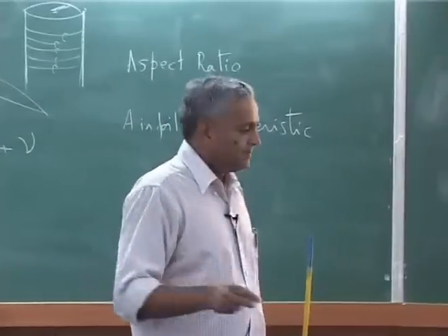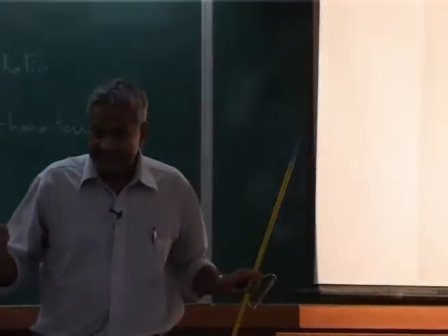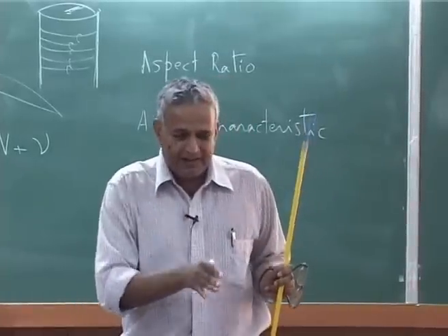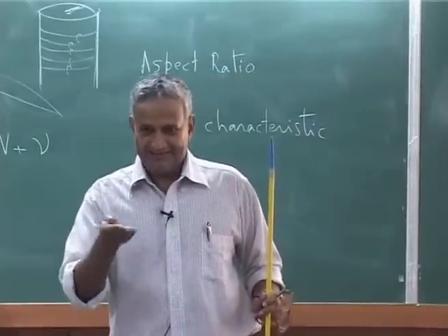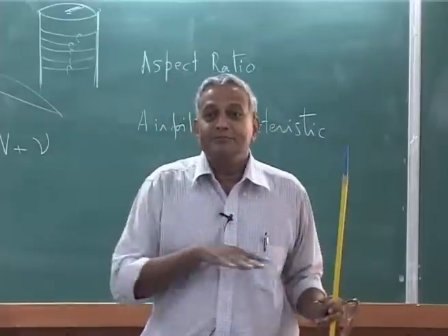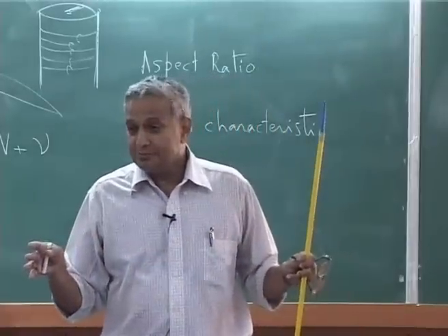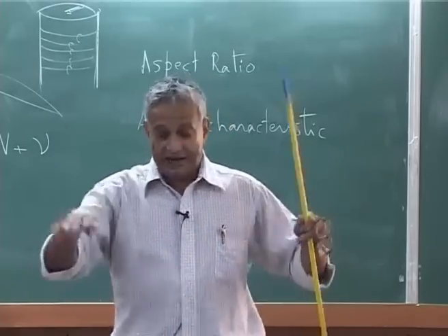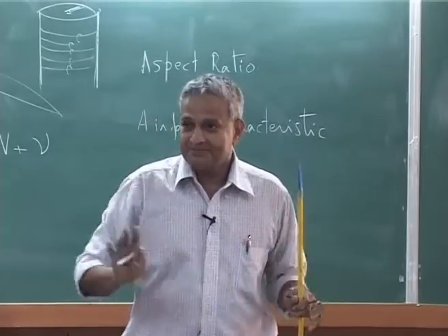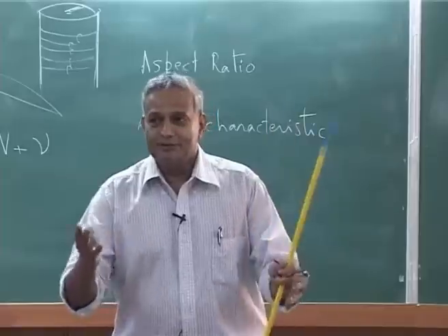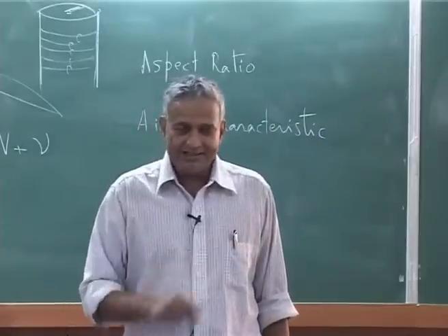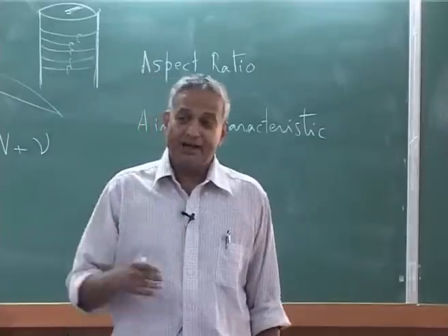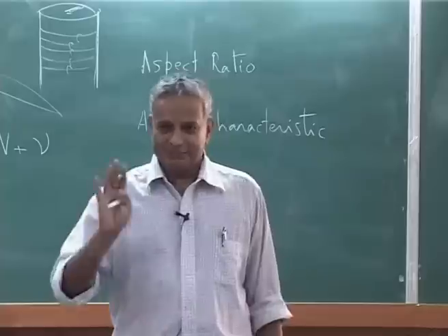But we will not use vortex theory, we will use simple momentum theory, and then we will complicate it, beyond the uniform inflow. That is what we did in the momentum theory: the flow over the disc is constant at every location, that is uniform inflow. Later you will see, that is too gross an approximation, let me have non-uniform inflow.